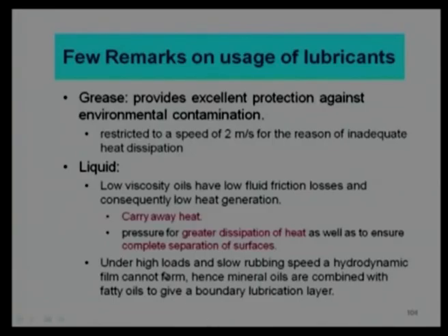However, if these low viscosity oils are not able to give good performance because of high load condition or slow rubbing speed, when the hydrodynamic action is not made, then we can use additives. In this case, we say mineral oils can be combined with the boundary additives, or can be mixed with the EP additives to give the desirable results to us.